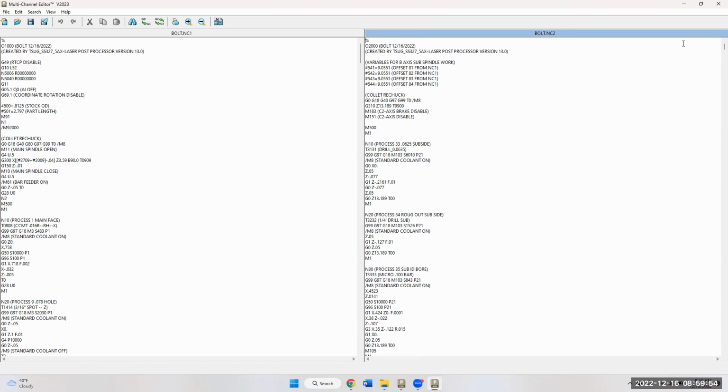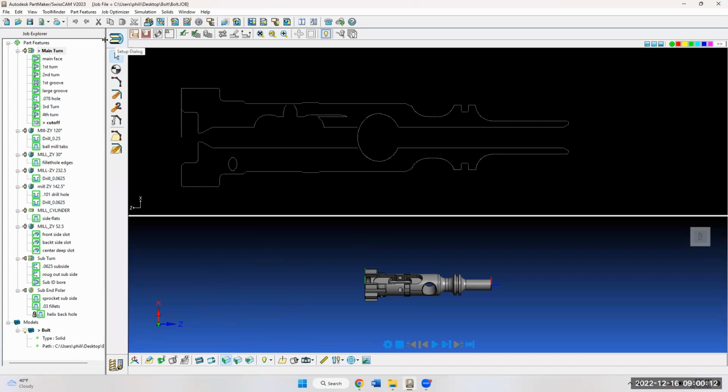Bring the model in, select your predefined construction planes to build the features around the part, generate your process table, reorder your processes, run your synchronization and your support functions, simulate, run code.